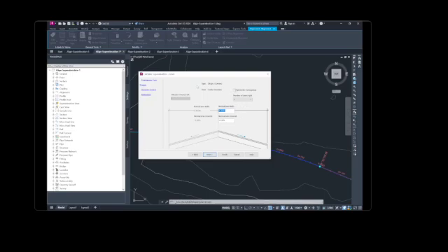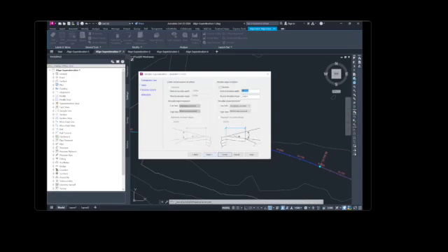And then in the Lanes section, we're gonna check the box. The Symmetrical Roadway is selected, number of lanes right 1, normal lane width 6,000, normal lane slope minus 2%. Click Next.